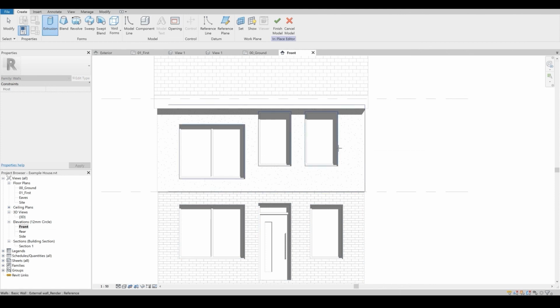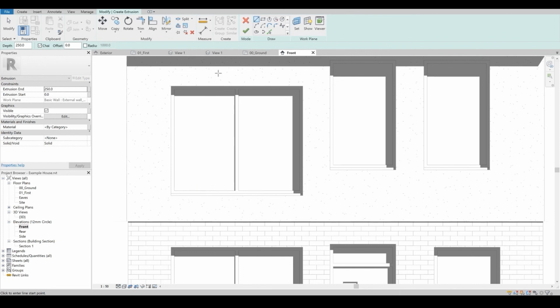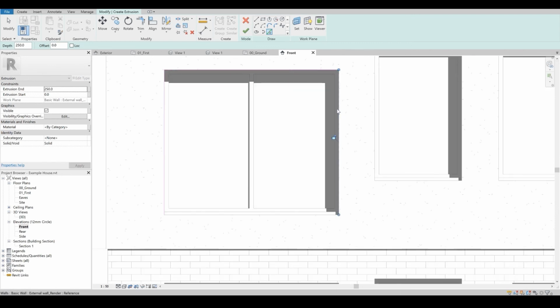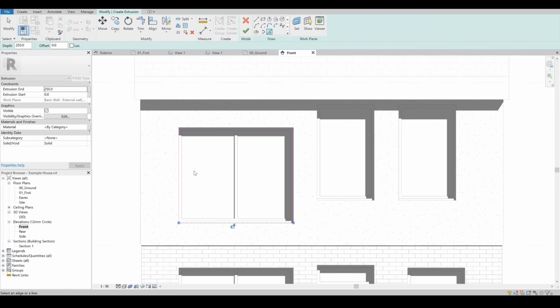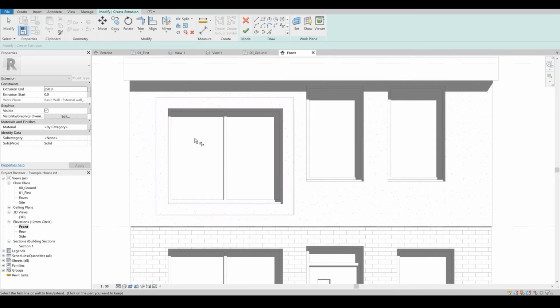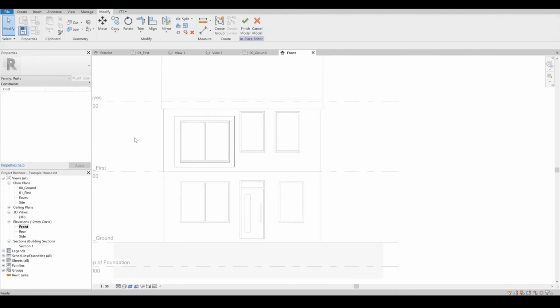We want to just select the wall we're working on. First, select the outer edges of the window. Then offset, I don't know, say 150, something like that. 200. Trim all your line work. Extrusion, you know, is 250mm. And that's how you make your extrusion.